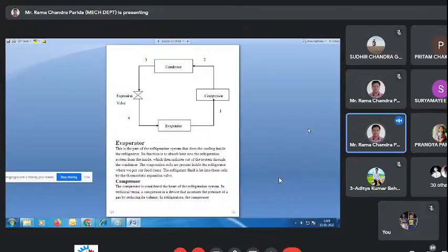We have already discussed the throttling process, applied to a steady flow process, in our past lecture. We have considered a steady flow device. It is a throttling device where there is an orifice or maybe a valve placed. The throttle expansion valve reduces the pressure of the refrigerant. On reducing the pressure, the temperature of the refrigerant also decreases further, to a level below the surrounding air.